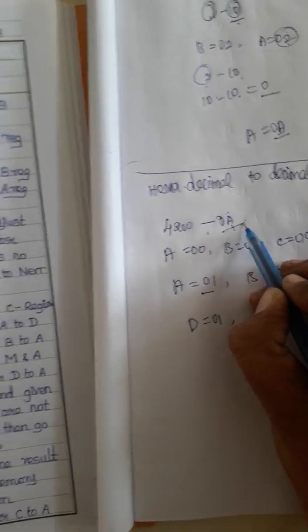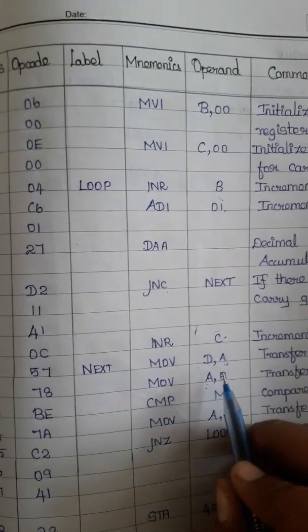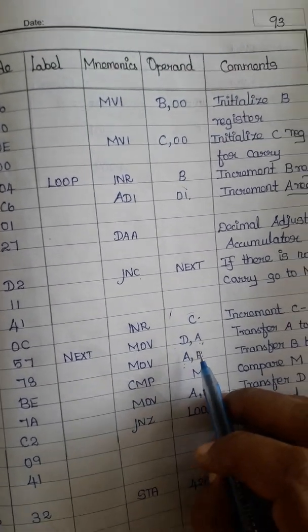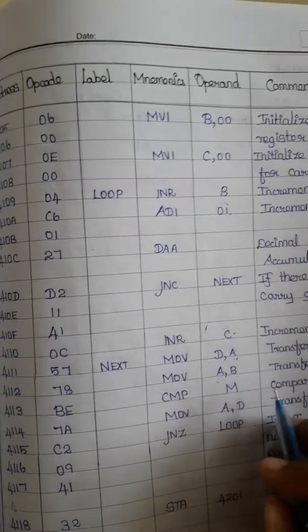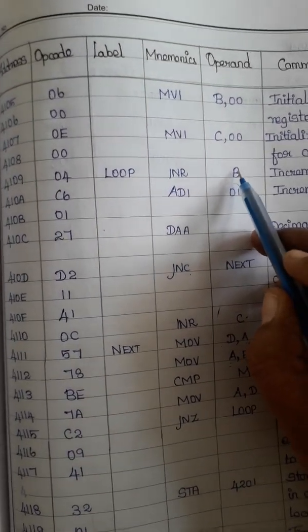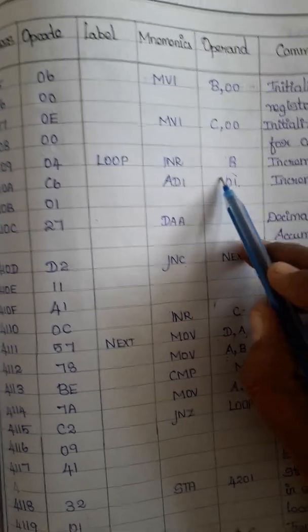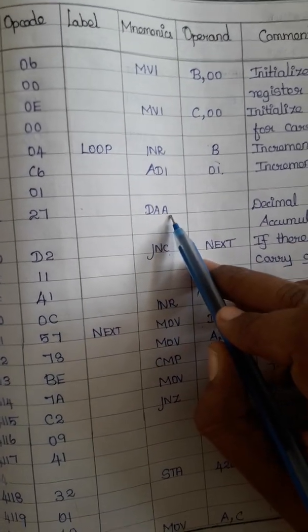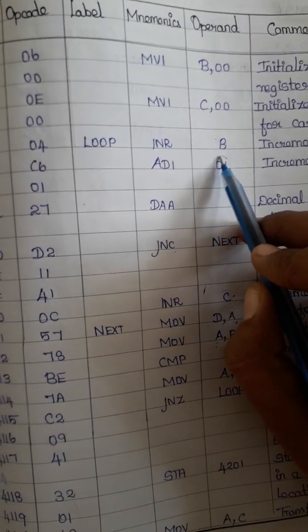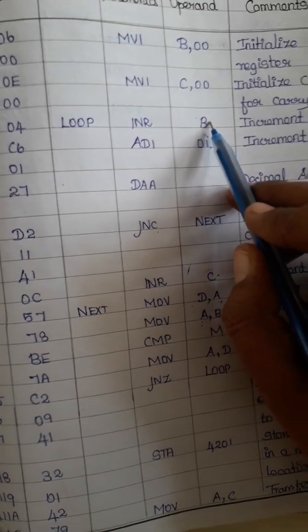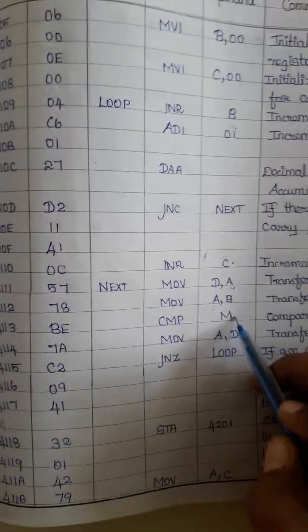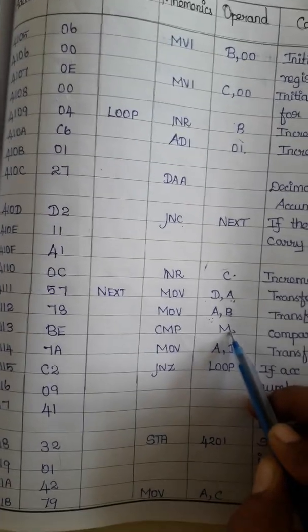Since in the memory location we have given hexadecimal data, in the accumulator we are in need of hexadecimal data. So for that we are moving the data which is available in the B register, which is the hexadecimal value, because the accumulator value is converted into decimal value. So now the accumulator's equivalent hexadecimal value is available in the B register. That data is moved to the accumulator and then compared with memory data.